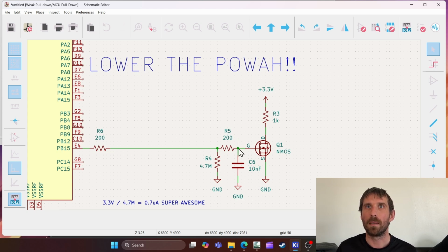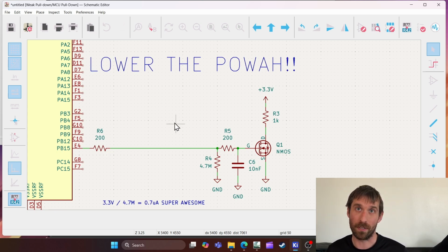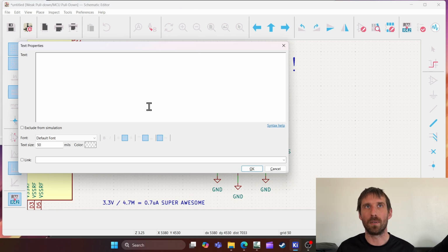Good design: make this trace as wide as you can, make it short. But if you can't, you can't. Sometimes I gotta have these over a foot long. That's over 30 centimeters for the metric people. So there's other things you gotta do. So, layout guidelines.